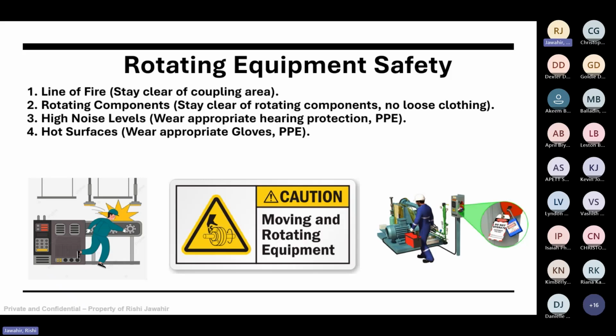So what we recommend for any job you're doing is to try to stand clear of coupling areas and the line of fire, especially on the startup of any rotating equipment, especially after any recent maintenance activities or intervention into the equipment. Always stand clear of the line of fire of rotating components. Especially for those in coveralls, always have the sleeves buttoned up, your gloves tightly placed, and no loose clothing. Also, with some equipment there are high noise levels.